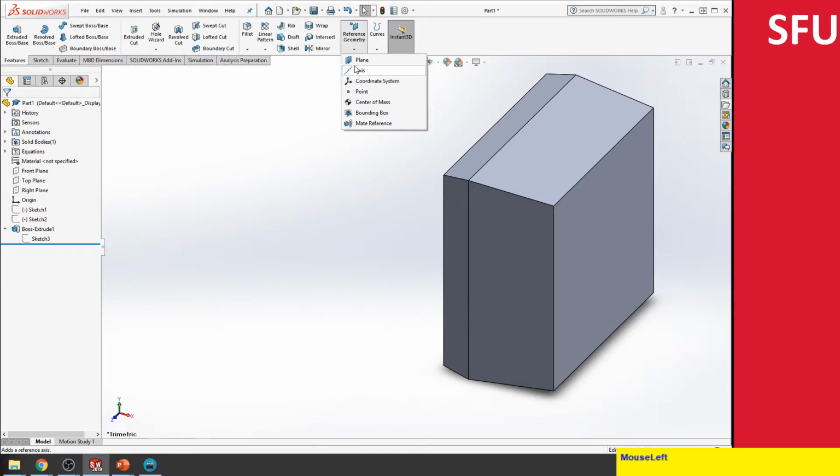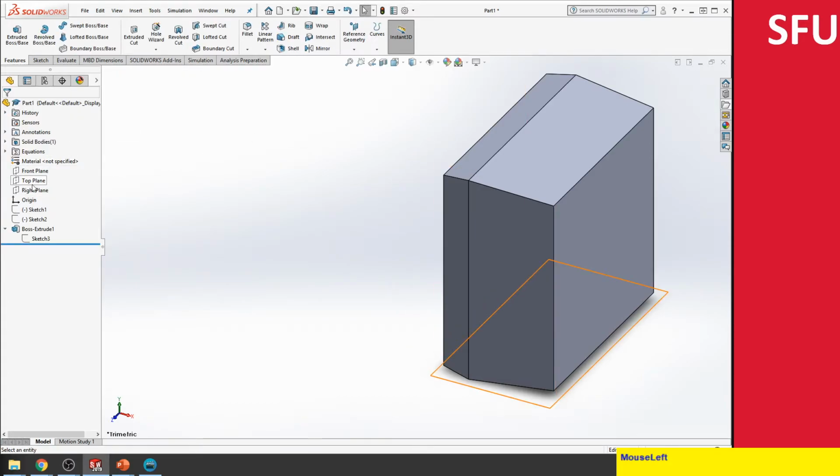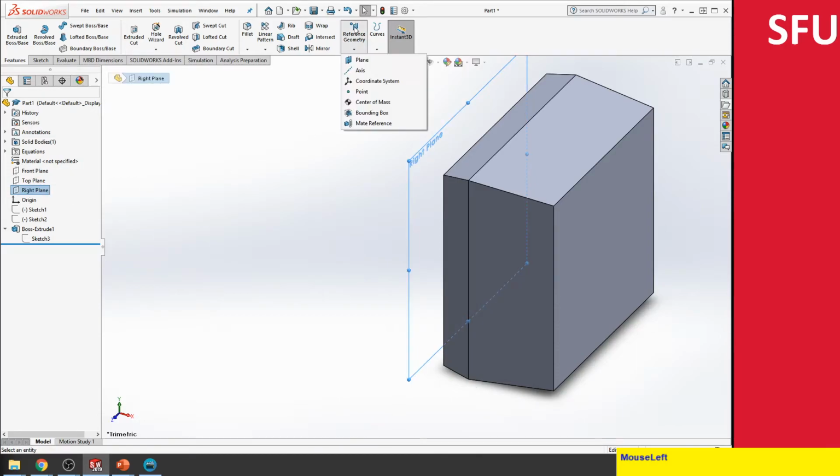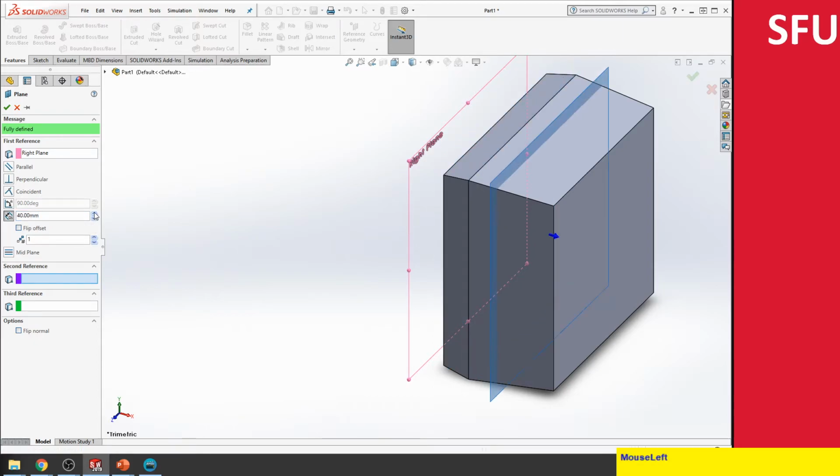You don't necessarily have to do it in this order. If you just randomly clicked on plane, then it will ask you more questions regarding the references and so on. Rather, if you started by selecting this plane and then selected the reference geometry, SolidWorks will interpret that you probably want to create an offset plane, and then it gives you the different options here. This would also show up if you just created the geometry as is. As soon as you select the first reference geometry, it gives the option. Anyway, once we do this, we can give the offset distance.